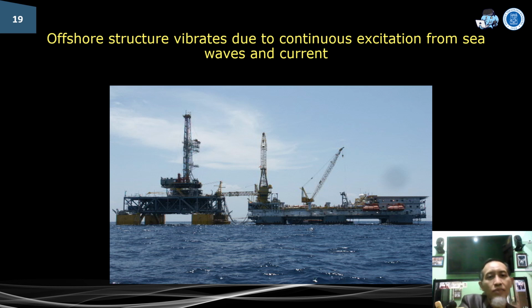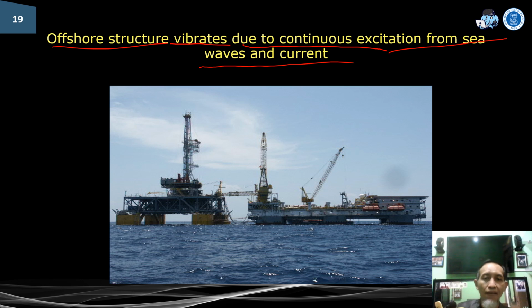An offshore structure vibrates due to continuous excitation from sea waves and current. Usually we design offshore structures for more than 100 years, and the critical issue is fatigue due to vibration.